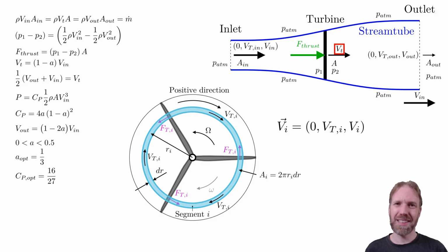At the turbine it's more complicated. In the normal direction, we could assume that the velocity is the same on both sides. This comes directly from the continuity equation when we assume incompressible flow. But we are not violating any physical laws if we assume that flow velocity turns at the turbine disk, and therefore have different tangential velocities depending on which side of the turbine disk we are. Hence, use the tangential velocity v_t1 before the turbine disk and use the tangential velocity v_t2 after the turbine disk. We will also add a third tangential velocity inside the turbine disk.